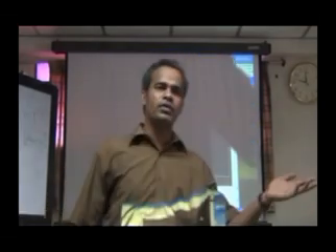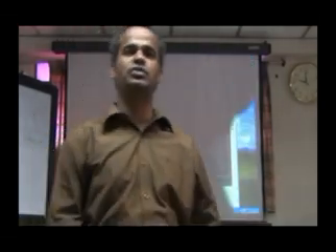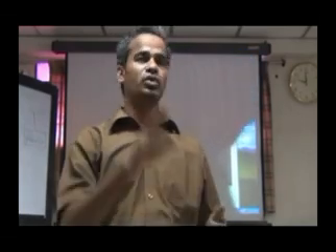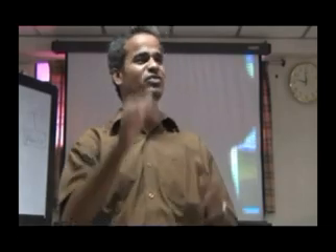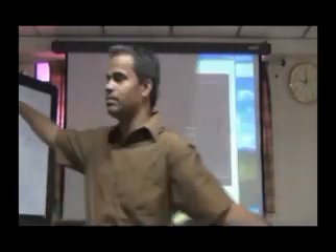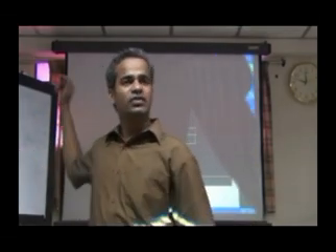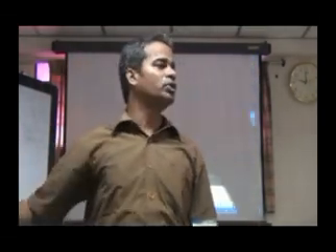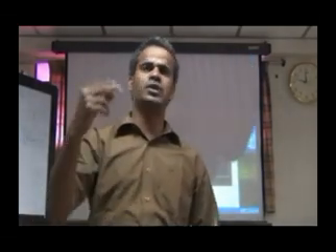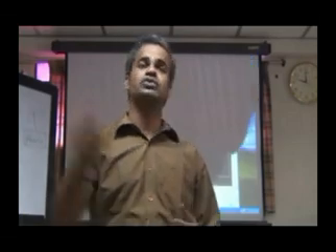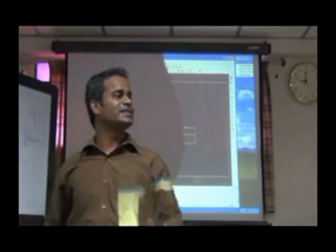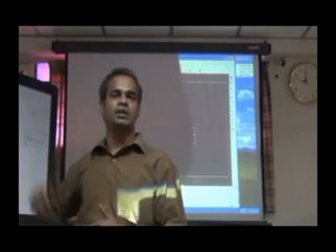In the CAM module you have different machines, different operating systems, control systems. Whatever machine you are going to use, I can key it in my CAM module itself. The model will be the same. Whatever tool you want to use, whatever accuracy you want, depending upon that you will be selecting the cutting tools. Everything I can specify in the CAM module, and I can generate the CNC part program in my CAM module.